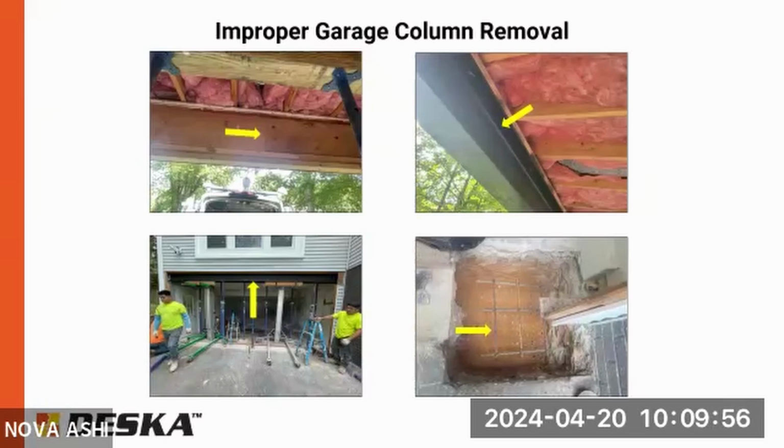You just make some assumptions as far as the weight. Are there tables that you can go to in structural books that say, if you have a 2-story with everything, this is what the weight would be in the middle of this span? Yeah, exactly that. In terms of dead loads, there's standard floor dead loads for certain size joists, subfloor types, flooring. Typical dead loads for a residential floor is between 10 to 17 pounds per square foot. The same with roofs as well, attics. And then in terms of live loads, typical residential live loads are 40 pounds per square foot.